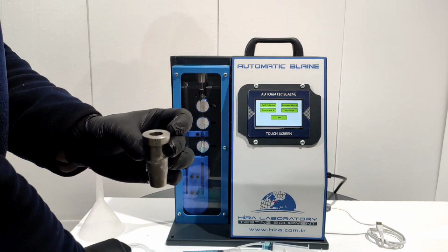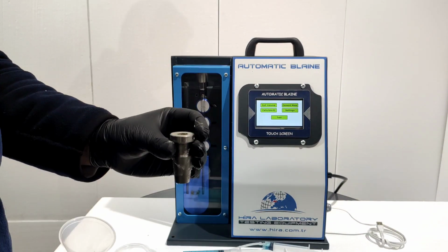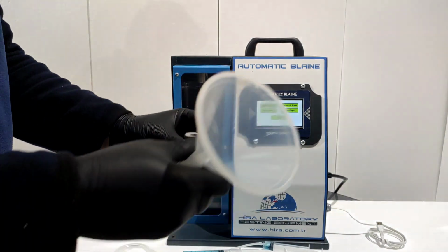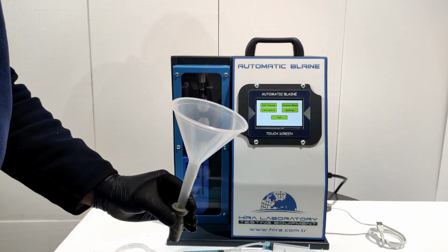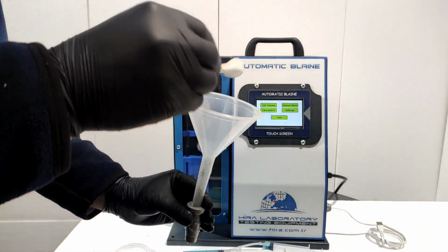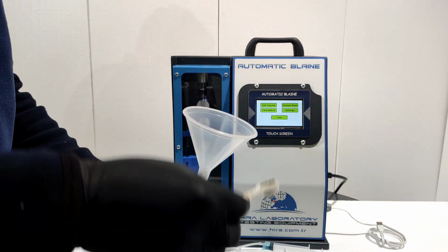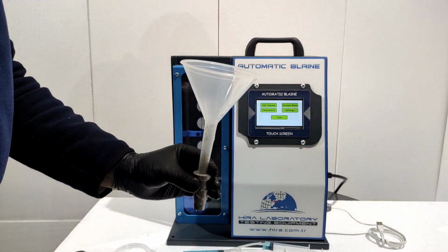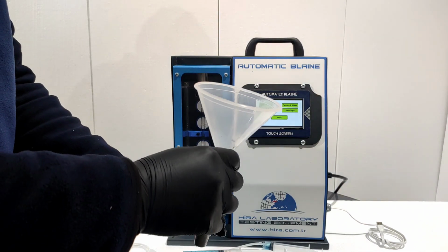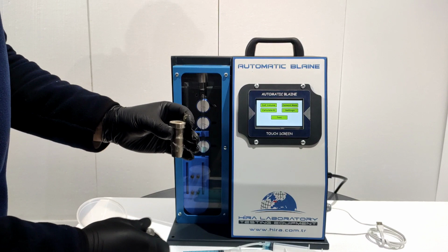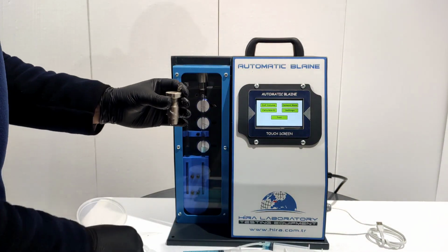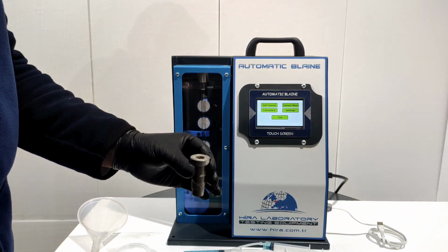Place the cell on a balance with an accuracy of 0.001 gram. Tare the scale. Fill the cell with the reference cement as much as the M0 amount you found in the formula above. Take the cell off the scale and tap the sides with the mallet to stabilize it. Put the second filter paper in the cell and tamp it with the rammer.